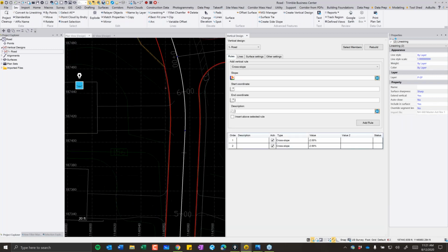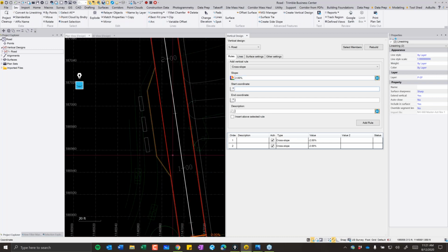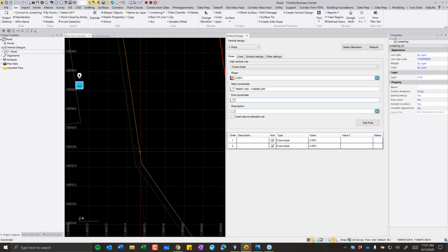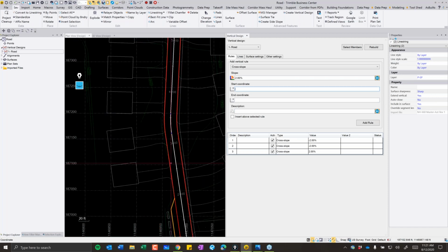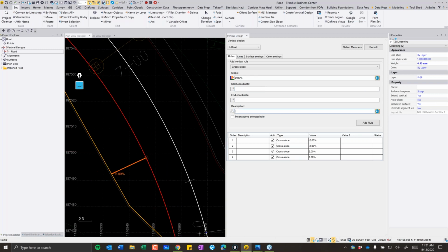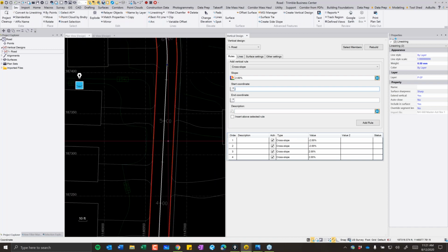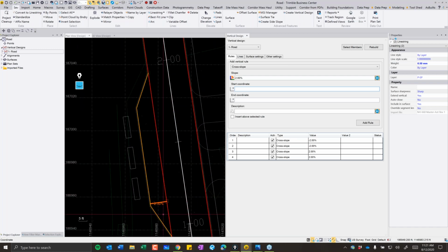So now that those have been added, I'm going to go through and add my instructions. The other nice thing I really like about this is you can actually see your instructions in plan view. Some of this stuff you could actually do with the corridor tool, but you're starting to bring everything all encompassing into the plan view, which is very nice. Because if you have different areas that vary, you can see that, or if the engineer has given you different cross slopes that vary, now you can bring in a PDF and overlay your instructions on where their callouts are and update that accordingly.